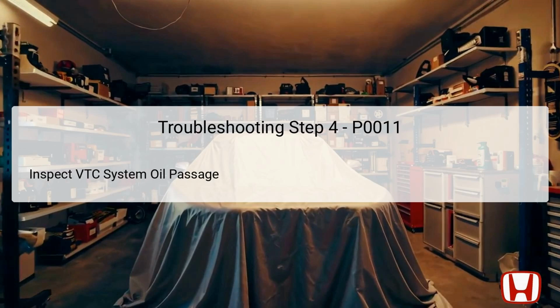The final troubleshooting step focuses on inspecting the VTC system oil passage for any blockages or debris. A clear oil passage is vital for the operation of the VTC components, as it allows for uninterrupted oil flow necessary for timely adjustments of the camshaft position. Technicians usually check for visible signs of clogging or contamination that could restrict fluid movement.